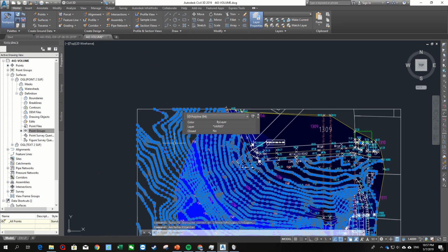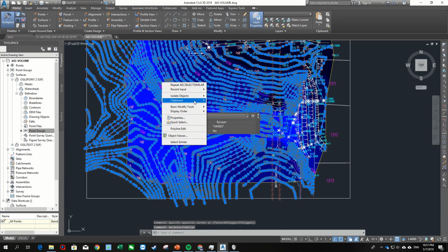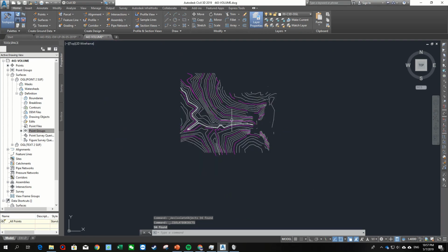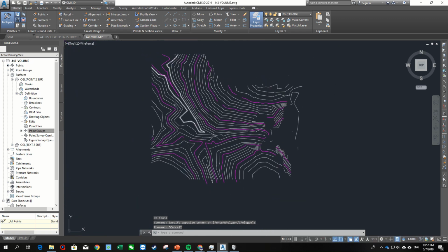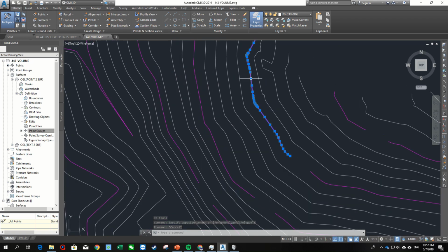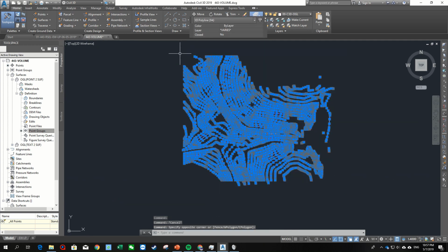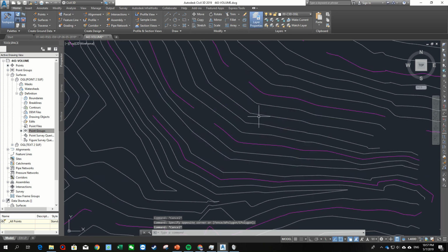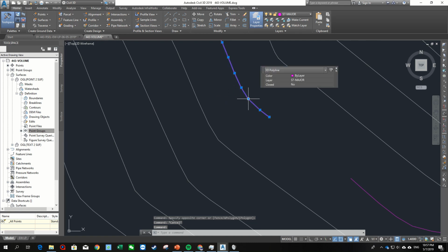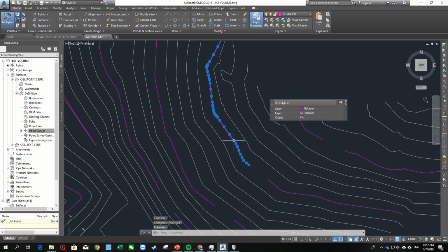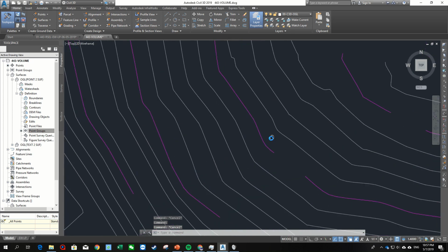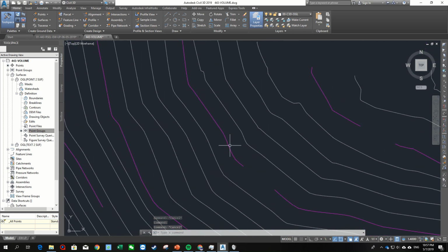Now you select similar. After that, same, right click, isolate the object. Okay, and these are the contour lines, and you have to see which is not 3D line, and you have to remove it. Okay, you have to make sure all others are just 3D polylines, which means it really have the levels. Okay, if you want to check whether these lines are in the correct value or not, actually you can do it this way.